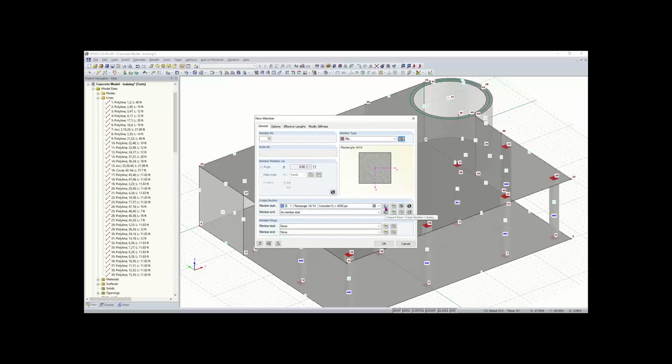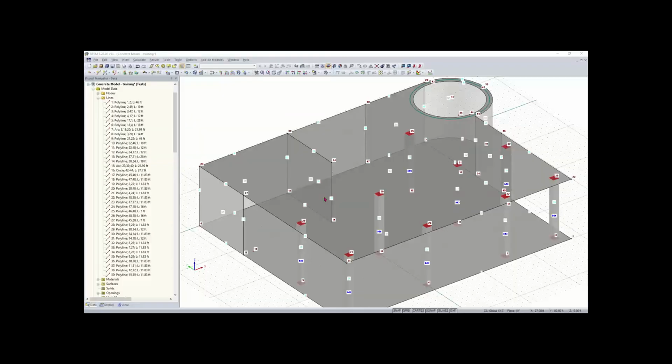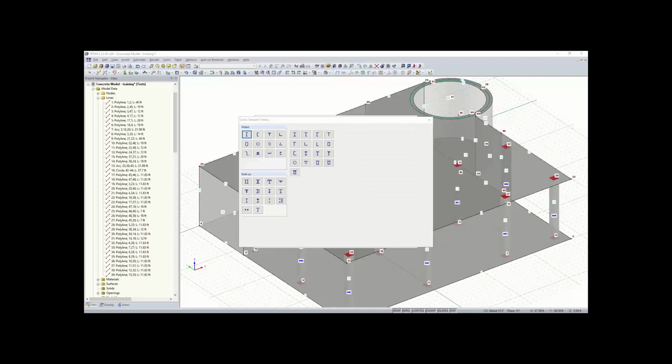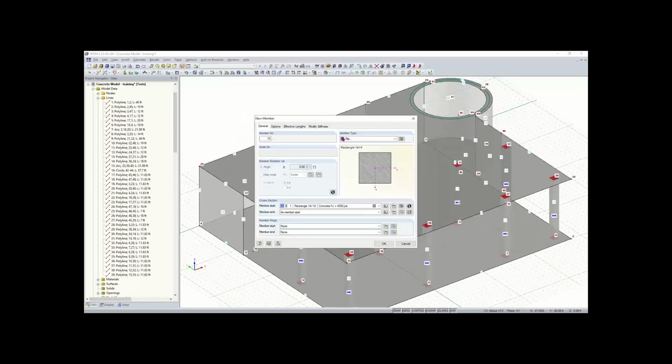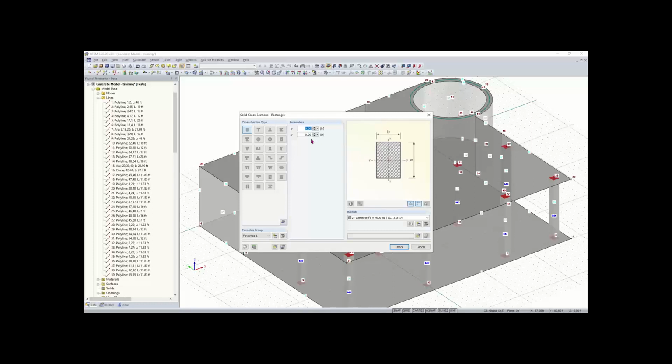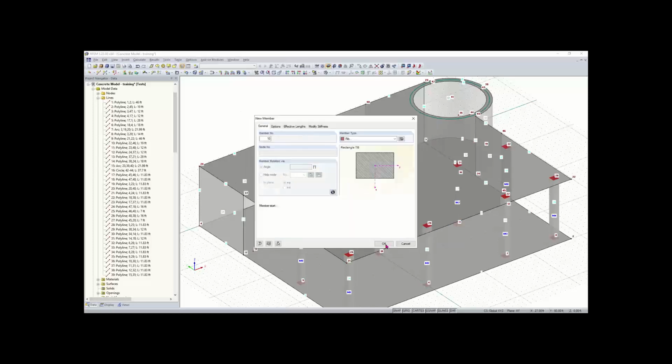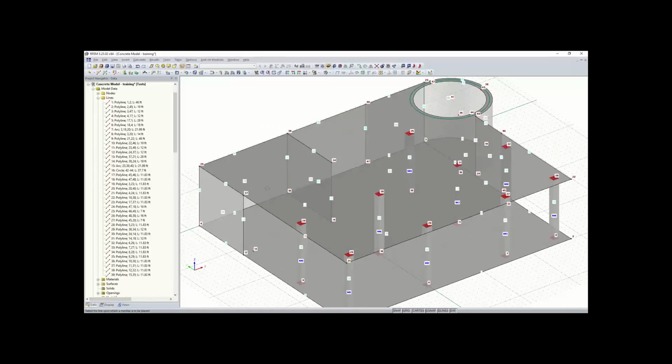And now I just need to change my cross section. And that'll load. So once I create my cross section here, it's going to be 7 by 5, parametric massive section. So it'll be 7 inches by 5 inches, 4,000 psi concrete. We can hit this drop down and choose the latest standard. We'll click OK. And again, we'll click OK. And now we can draw.